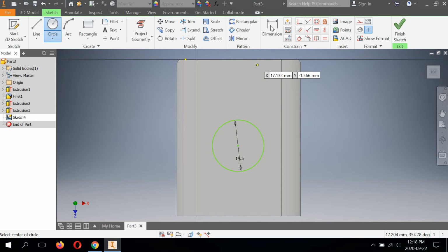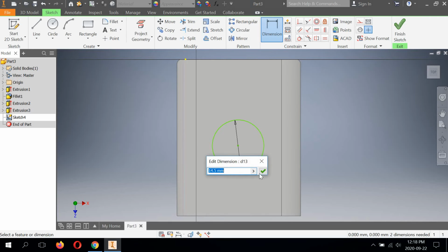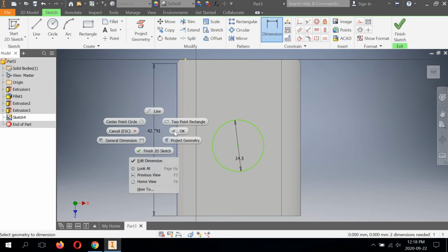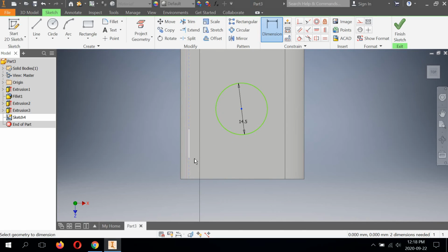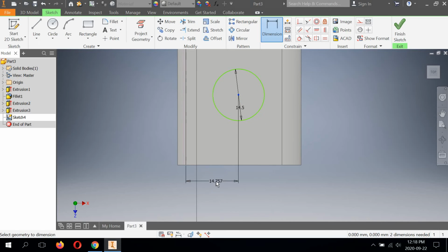And I'm going to dimension this from here to here, right? This line represents the inside thickness. Remember, this is dimensioned on the inside, from inside face to inside face 30. So that means this will have to be 15.